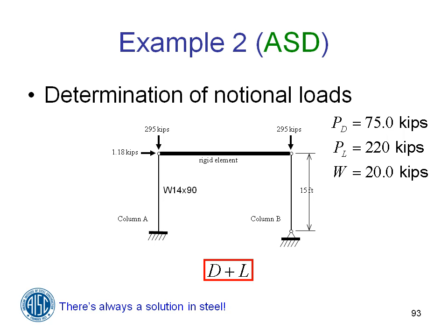Even if our B2 is less than 1.7, we still have to have our notional load in the gravity-only load combination. So here it would be 1.18 kips. Now the reason that I didn't use the alpha of 1.6 here is because if we do the B1, B2 method, the alpha is in the B1, B2 calculation, and it doesn't need to be put into the load combinations. Because what happens when we do an analysis with 1.6 times the ASD load combinations, we then divide by 1.6. And of course, if we're not doing a second order analysis, the dividing just cancels out.